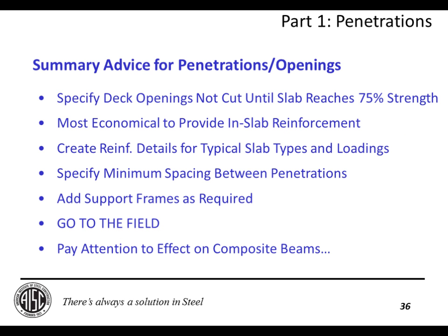So as a summary, for penetrations and openings, you should specify that the deck openings not be cut until the slab reaches 75% of its design strength. It's most economical to provide in-slab reinforcement where you know where the openings are going to be. It'd be a good idea to just go ahead and go through that model I showed to create reinforcing details for your typical slab types and loadings. You should specify a minimum spacing between penetrations to try to avoid the situation I showed in the opening picture. Add your support frames as required.